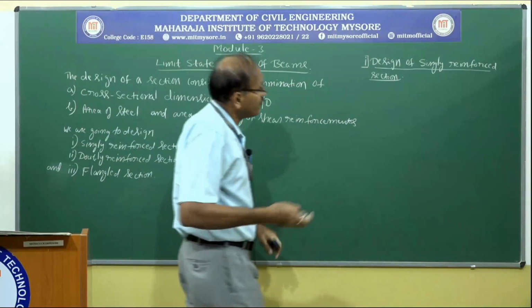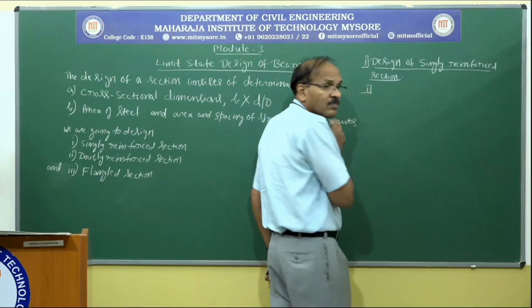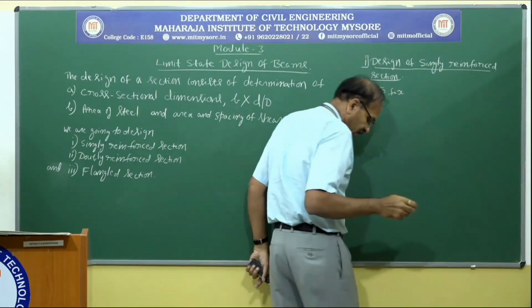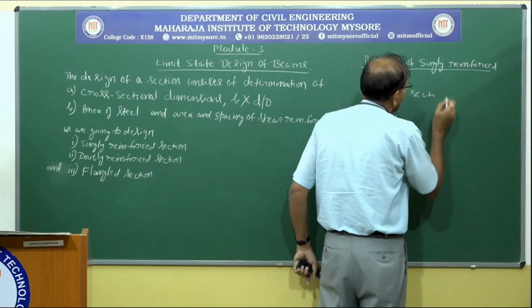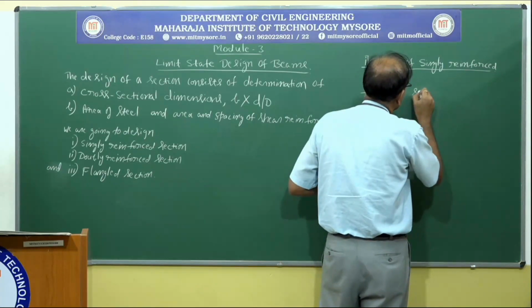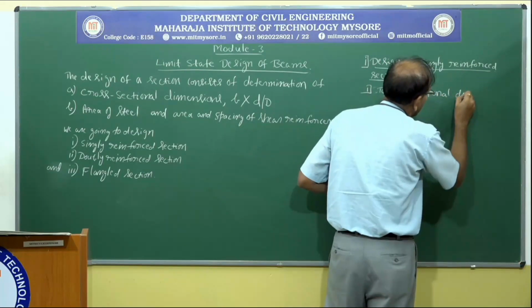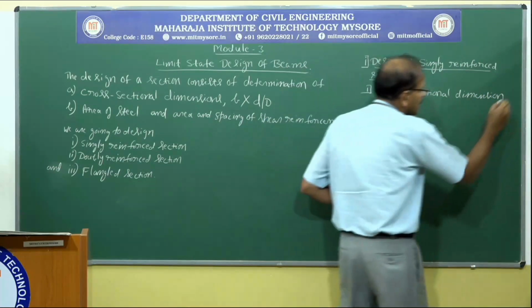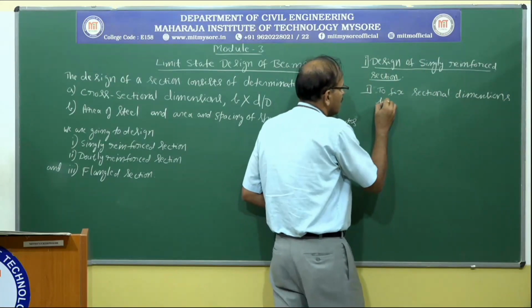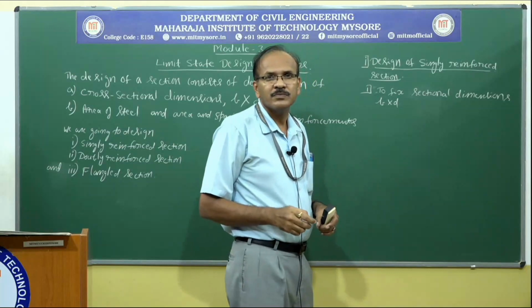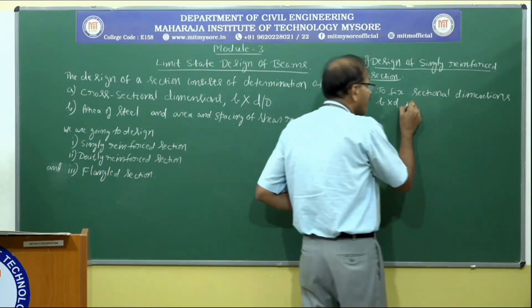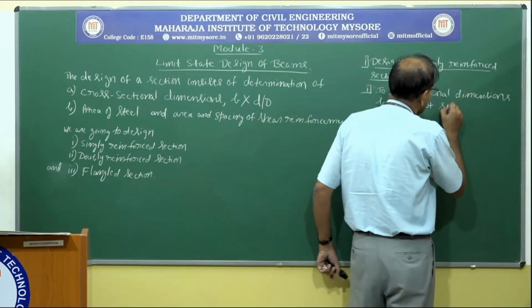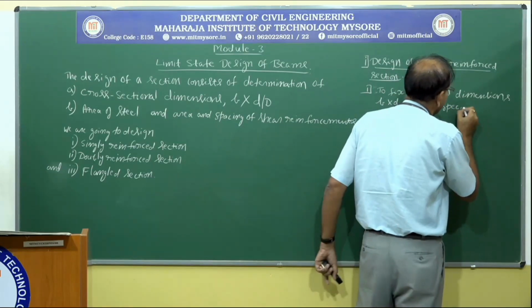So here, the design of a singly reinforced section: to fix the sectional dimensions B by D, if not specified already.